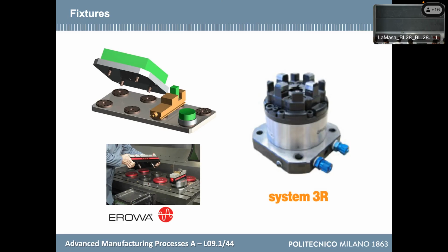There was a nice demonstration in manufacturing processes 1. So if you attended here at Politecnico, maybe you remember it. There was a demonstration in foundry about the presence of cracks when the part decreases its temperature in a mold of foundry. And what I have said is strictly related. So what you can do is having a good material, so you should apply a thermal treatment, so it is completely relaxed, so you don't have any fear then.